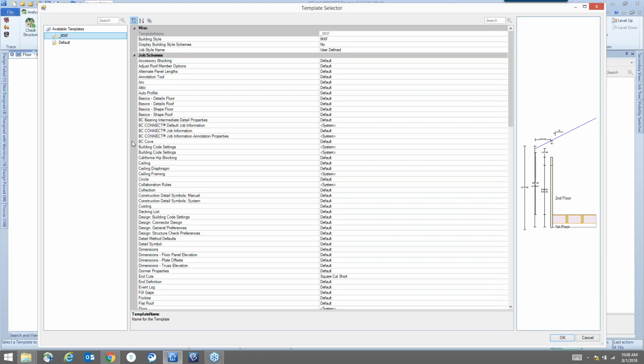And one of the keys here, as you're working with that building designer, is you're getting used to the way that they design the wall heights. They may design 2x6 walls on the first floor and 2x4 walls on the second, floor depths and that type of thing. So you can start to predefine templates here and have everything set up for you, so the time it takes to import one of these models is very minimal.